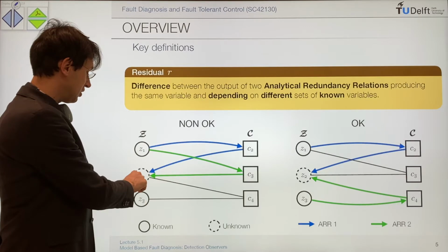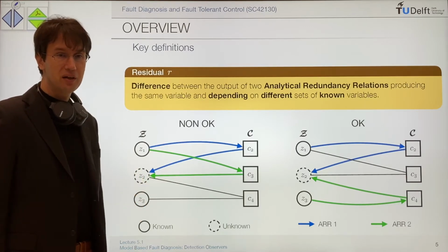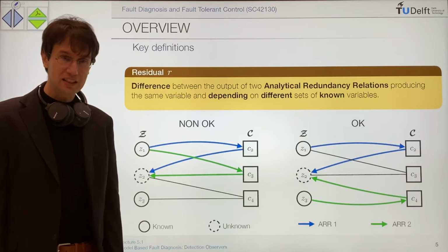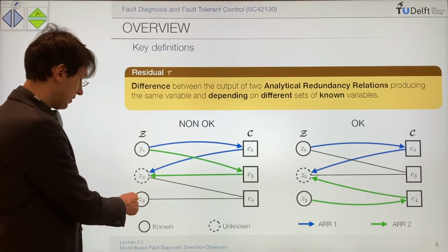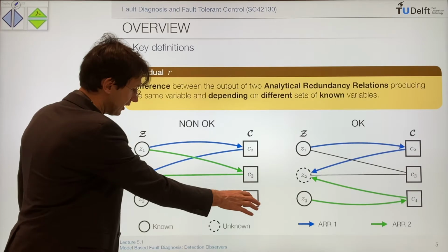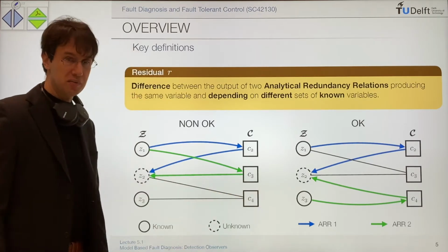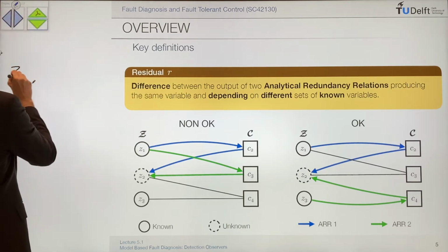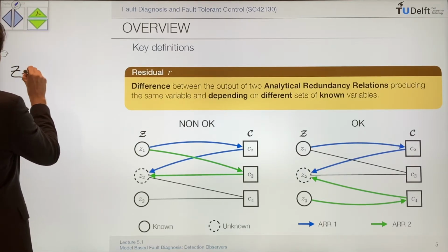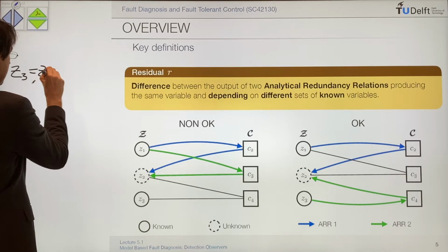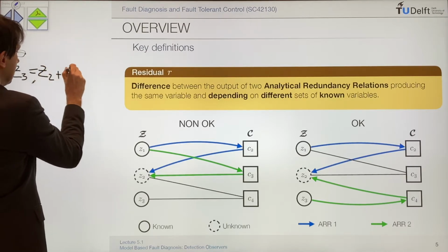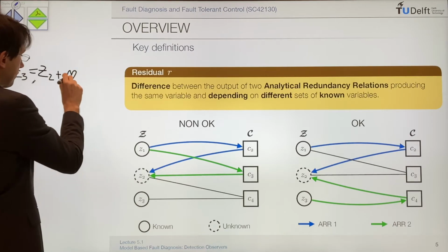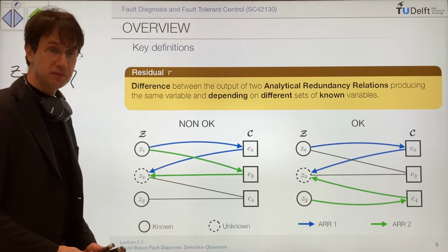So here Z2 is representing the state variable, which is actually unknown. We have no access to the actual state, but we have access to measurements. And C4 then is the equation implementing the measurement. And C4 can be as simple as saying that Z3 is equal to Z2 plus some noise, and let us call this noise eta. So eta is some random variable representing noise.